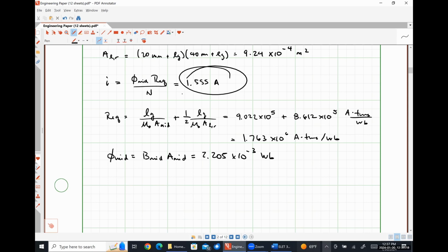But does anything about this process seem incorrect? Let's start there. Numbers are arbitrary. That's just a calculation error. Does anything about determining my equivalent resistance or reluctance seem suspicious? It's just the reluctance of the middle air gap plus half the reluctance of the left or the right air gap, because those two air gaps appear as if they were in parallel to our MMF source. Okay. So this equation seems appropriate.